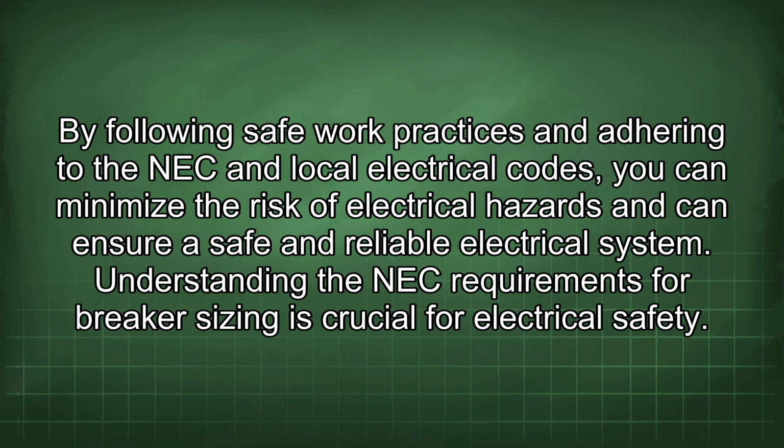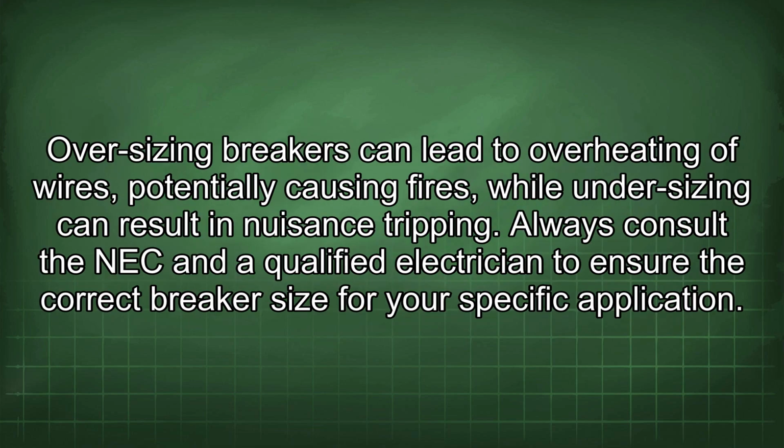Understanding the NEC requirements for breaker sizing is crucial for electrical safety. Oversizing breakers can lead to overheating of wires, potentially causing fires, while undersizing can result in nuisance tripping. Always consult the NEC and a qualified electrician to ensure the correct breaker size for your specific application.